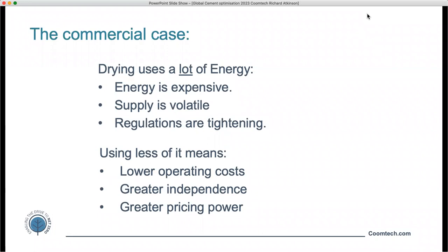So that takes you through the operating principle and configuration of the system and explains why it yields the energy savings that it does. Fundamentally, it's this. It takes less energy to blow water off than to boil it off. Now, I am going to say here that, as I noted earlier on in this talk, drying is a highly segmented sector with many different sectors for correspondingly different needs. There is not, and isn't likely to be, one drying technology to rule them all, and the kinetic dryer is likewise well suited to some situations and less so to others.